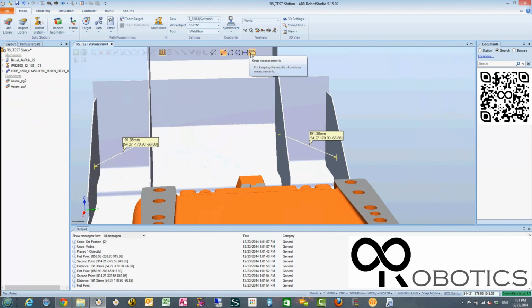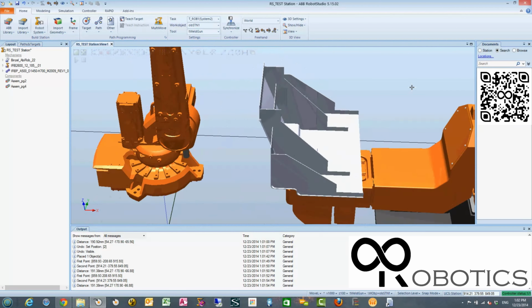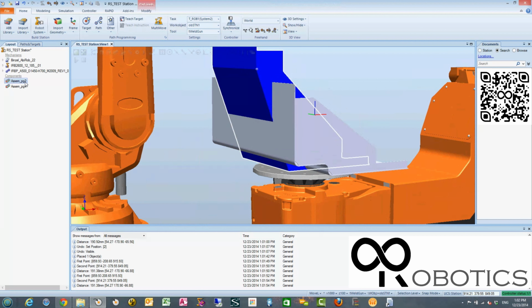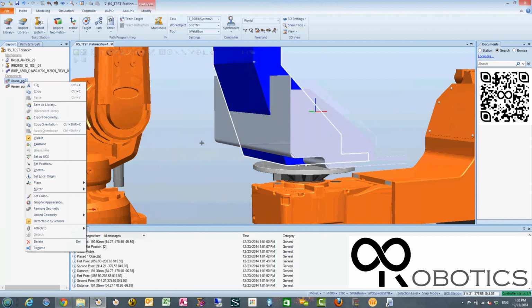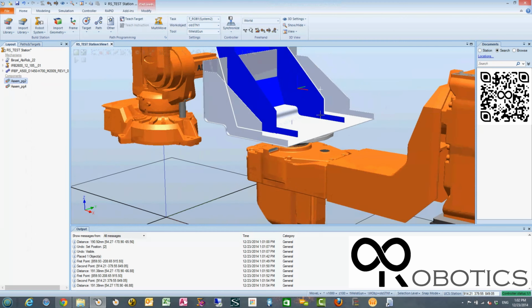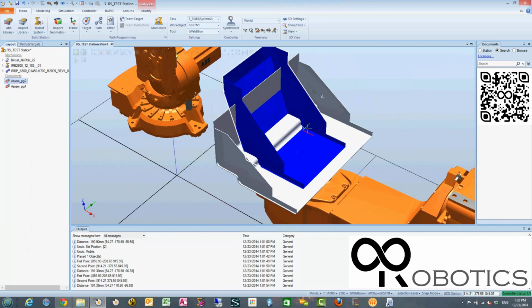So that's a lot more convenient than doing math to try and figure out where this should go. So that's how you move parts around. Now the other thing you can do here is setting the local origin of parts. Setting local origin is helpful because here's the local origin here when attaching a part to a position or attaching it to something else and moving it around.